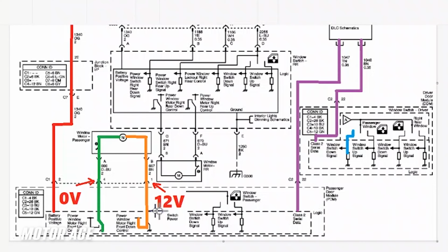And what's not drawn here because it continues on another page, but rather than switching pages, I'll just draw it there for us, is a path to ground. So we have a brown wire, which is going to be energized at 12 volts when we push down. Our dark blue wire at our connector number 1 should reference near 0 volts. And a black wire, which, again, I've drawn here, but it is not present in this picture, should always